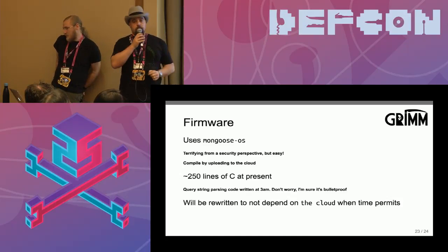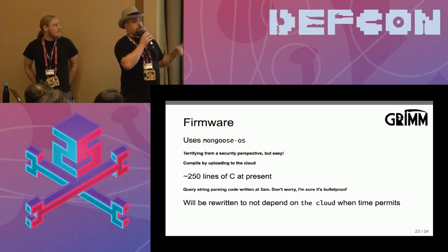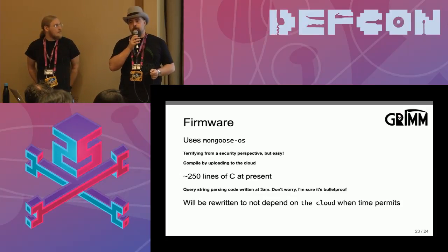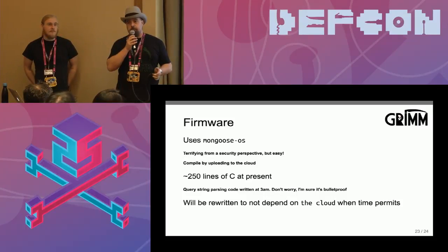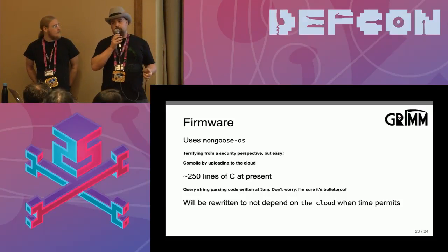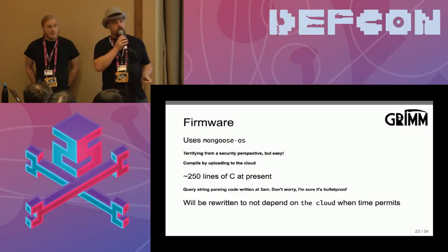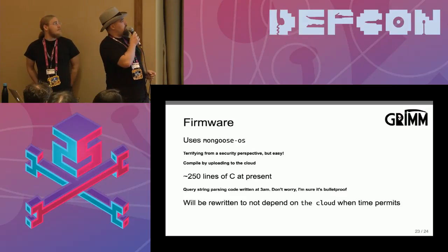Yeah, just make sure if you do get a CAN transceiver, the ESP32 is a 3.3 volt part, and most CAN transceivers that I've seen are 5 volt parts. Just make sure that you get a 3.3. If you just pick up a random CAN transceiver, it's probably going to be a 5 volt part. So make sure you get a 3.3 volt transceiver.